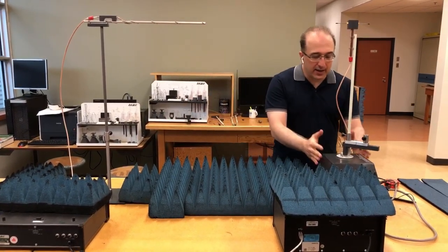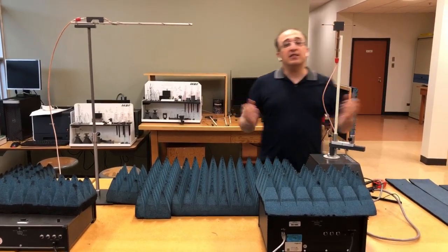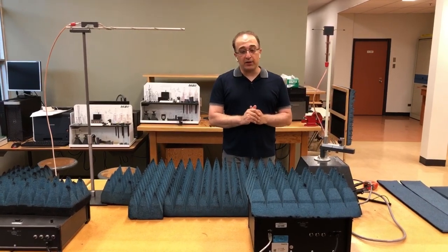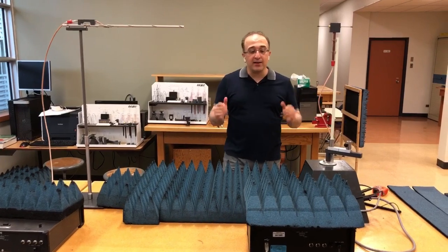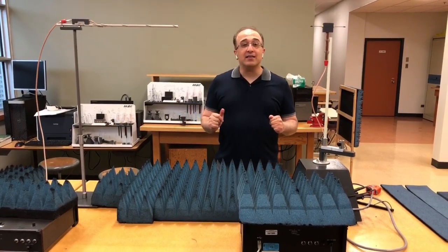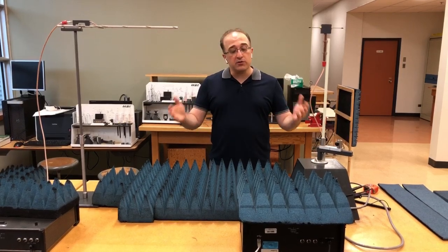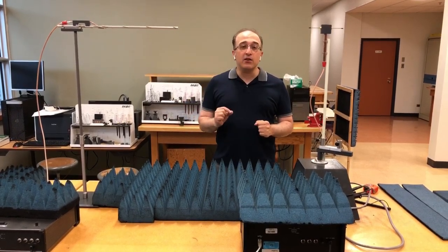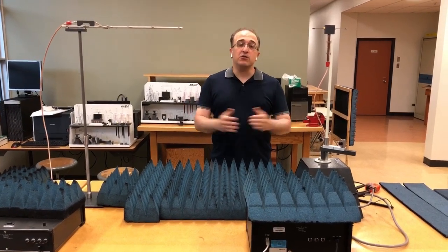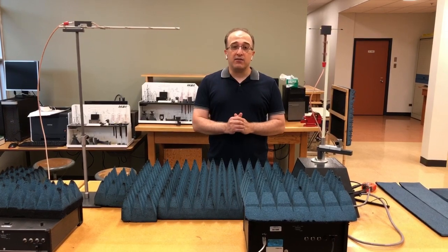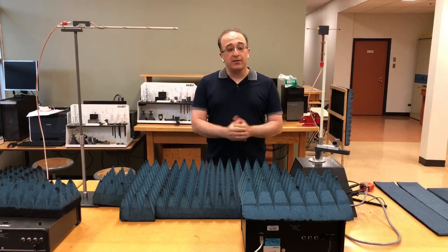The second measurement, I take the receiving antenna and I move it a little bit farther, and then we see what's going to happen. Remember that ideally under perfect far field condition, the pattern of the antenna should stay the same. And when I say pattern, that means angular distribution. Of course, when you are measuring the received signal, it's expected to drop based on the Friis equation as soon as you increase the distance between the transmit and receive antenna. But for example, half power beamwidths should stay the same.